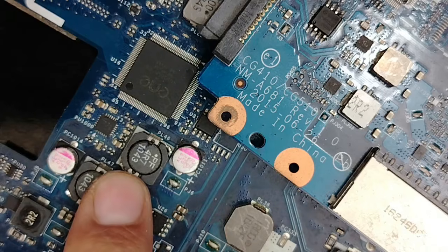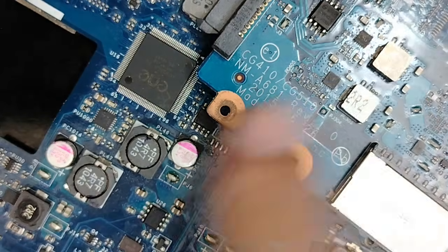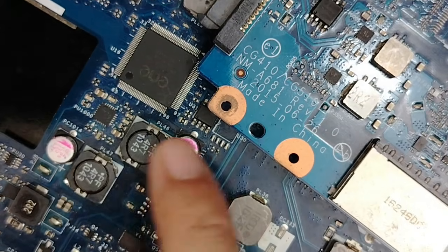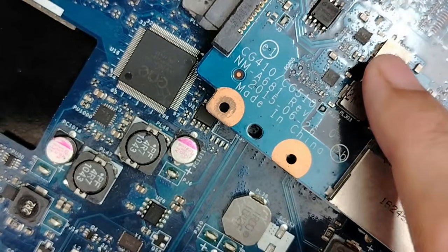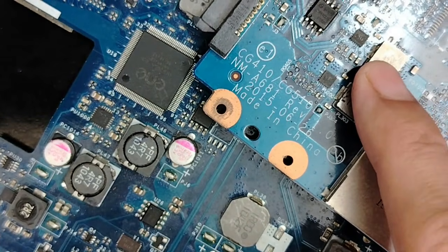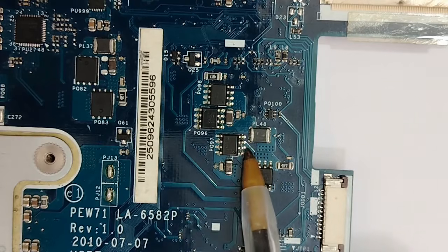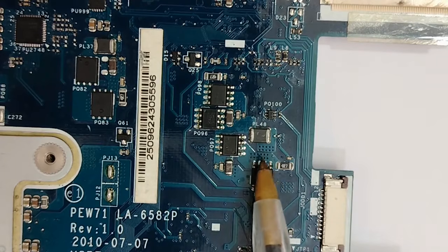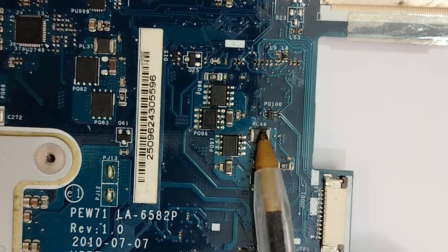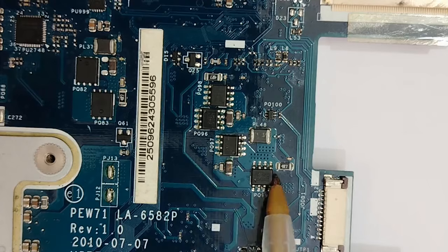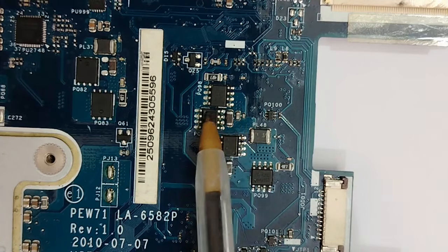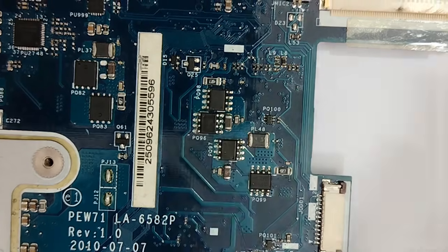So guys, we have this circuit and this circuit. Let's begin, for example, with this circuit that contains the MOSFETs, draw its schematic, and then draw the schematic for this motherboard also. So let's begin with this motherboard, guys. At the input we have PL48, where we have 19 volts, and we have 3 ceramic capacitors for this channel, 3 ceramic capacitors for this channel, 2 MOSFETs.